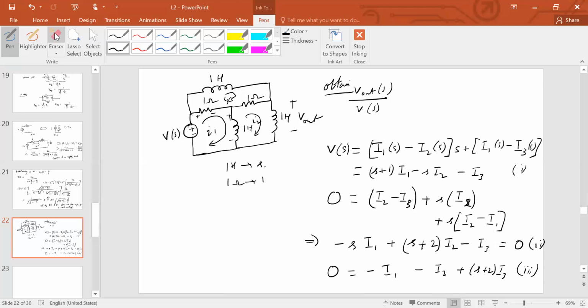That actually brings to attention this mistake I had made. This way you can never go wrong. So I'm glad I made that mistake because that just illustrates the point that there is a shortcut. So it's just 2S plus 1 times I2. Now similarly, for the third loop, you have S plus 1 plus 1, that's S plus 2, appearing as the coefficient of I3.